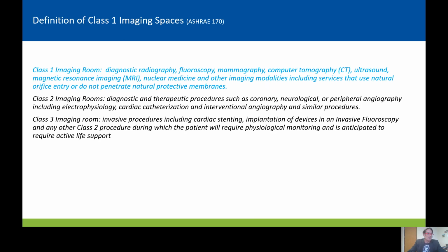Okay, so in October 2019, ASHRAE Standard 170 changed the name of X-ray Diagnostic and Treatment, which was the previous name, to Class 1 Imaging Room. And at the same time, we added these definitions. Class 1 Imaging Room is diagnostic radiography, fluoroscopy, mammography, computed tomography, ultrasound, MRI, nuclear med, and other imaging modalities, including services that use natural orifice entries and do not penetrate any natural protective membranes.